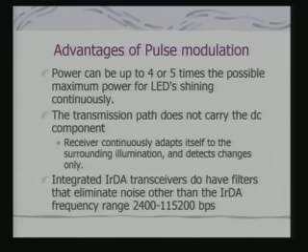Integrated IRDA transceivers do have filters that eliminate noise other than the IRDA frequency range. So other noise is eliminated. This detection becomes important and critical in view of the surrounding illumination as well as the noise sources. And in fact, if you have used such a link for transferring data, you will find a slight disturbance. In many cases, there are disturbances that cause the data to be interrupted, and in various ways you will find that message coming up.